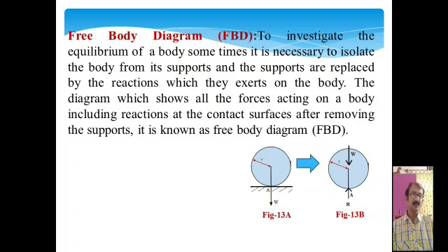In figure 13.a, it is clear that the sphere is resting on the horizontal plane, and the weight of the sphere is W, and A is the contact surface. If we remove the contact surface, the reaction force will be R, that will be upward, and W is the downward weight. So in this case, the reaction force R equals W, as in figure 13.b.